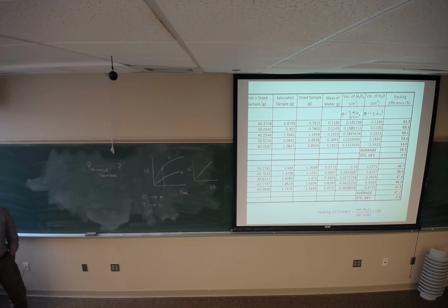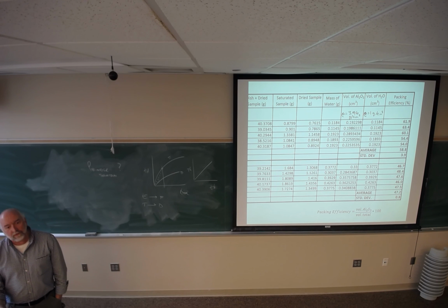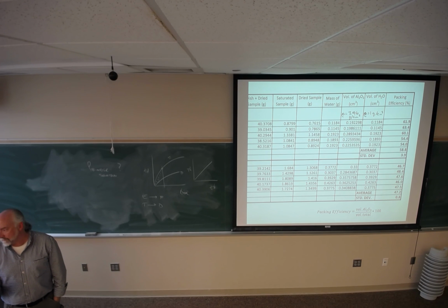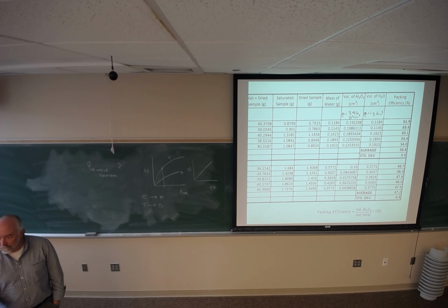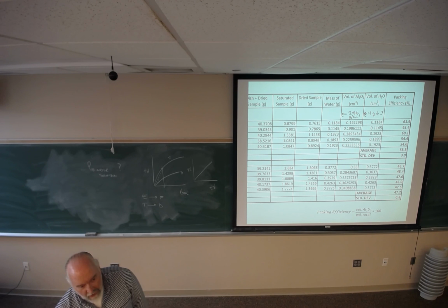So in the lab, you'll see them in the lab, there's a bunch of graduated cylinders sitting around with funny colored fluids in them. We are measuring the densities of polymer solutions. And that's how you do it. You make up a polymer solution with a known amount of polymer in it, and then you weigh it, and then you put it in a graduated cylinder and get the volume. Good? And that will give you the density. It's very likely, because our polymer solutions are relatively dilute, that you have no correction for density. Okay? If you were in a more concentrated condition, then you have a correction for density.